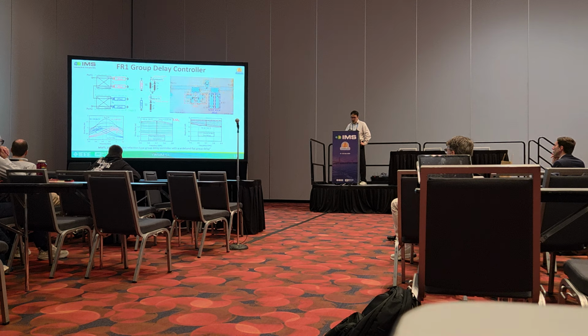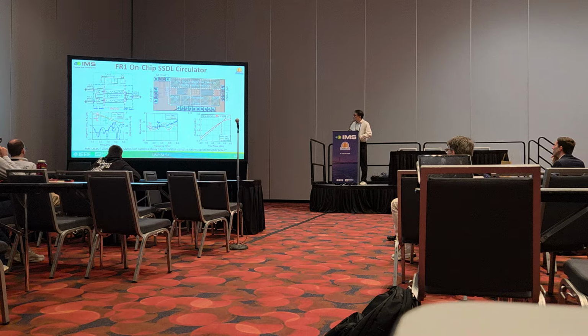We have another delay element here. By adding these two together, from port 1 to port 2 we experience two delays. So at the center frequency, we have flat delay. By changing this load, we can achieve delay variation, and over the delay variation, we're not going to have much magnitude variation. So delay can be controlled by this delay controller. Actually, there is no well-known name for this group delay controller. We started to call it GDC, but anyway, this is how we can change the delay.